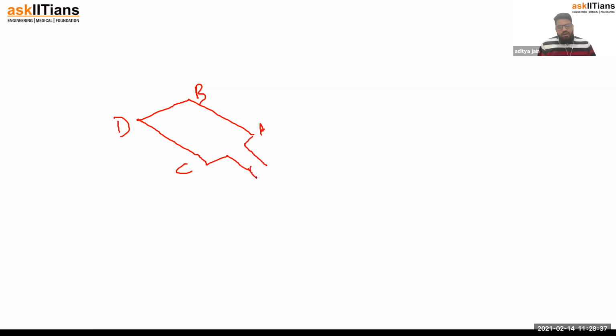This was the split ring, and you know the split ring moves with the coil. So now this has become Q, this has become P, because initially it was P. P is attached to arm AB. So that's why P comes here and Q comes here. But the carbon brushes are constant, so this is X, this is Y.